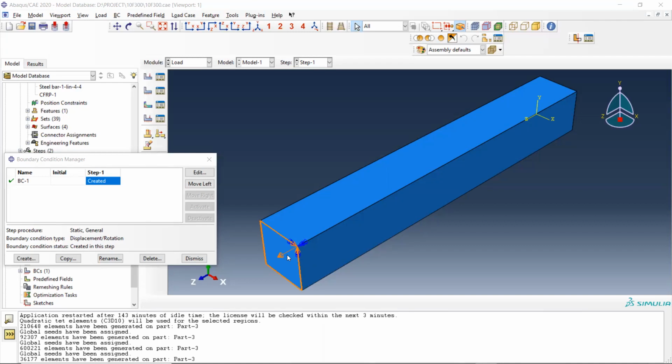Okay. Actually, what I was trying to do is to create a reference point here in this plane. It's a lateral node. The load will be applied laterally. It's a column, so cyclic load just to simulate an earthquake. You create it in the middle of that, and if you want, you can apply the lateral load also.